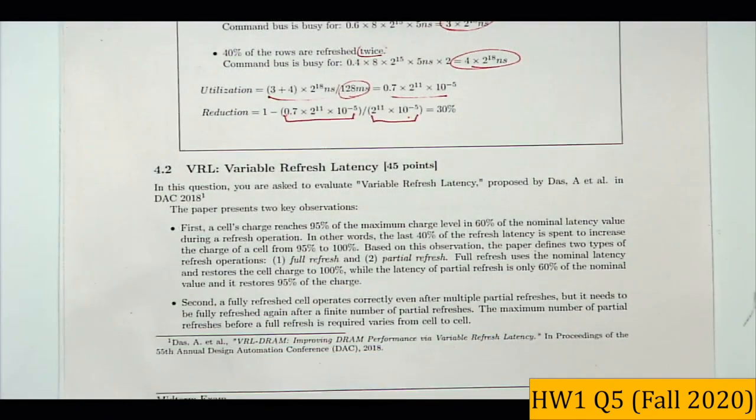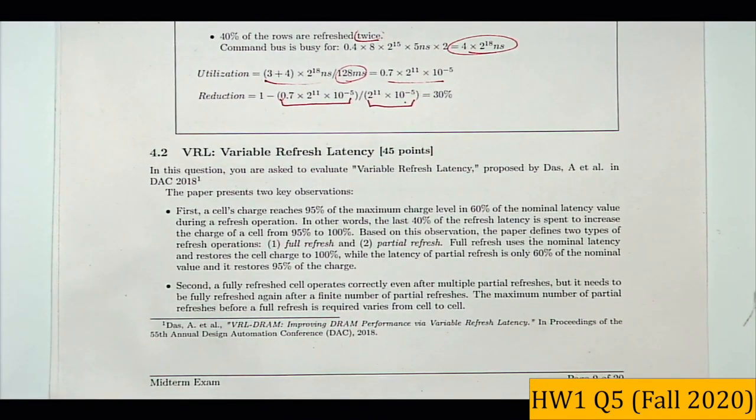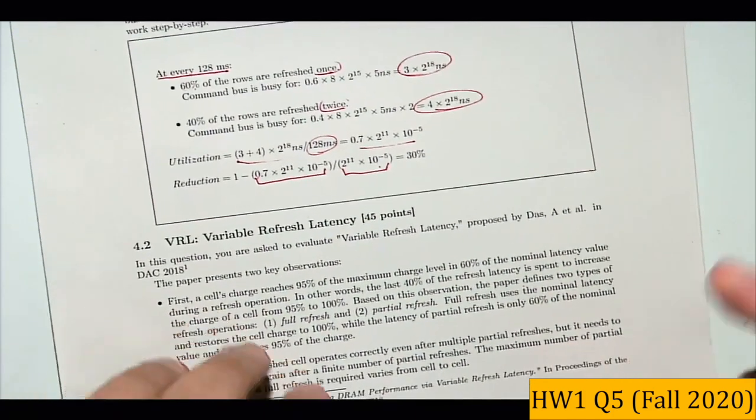So this is based on a paper published in 2018 DAC. It's variable refresh latency. The main observation in this paper, as we described in the question, is that you don't have to wait for the full refresh latency. So what is refresh latency?